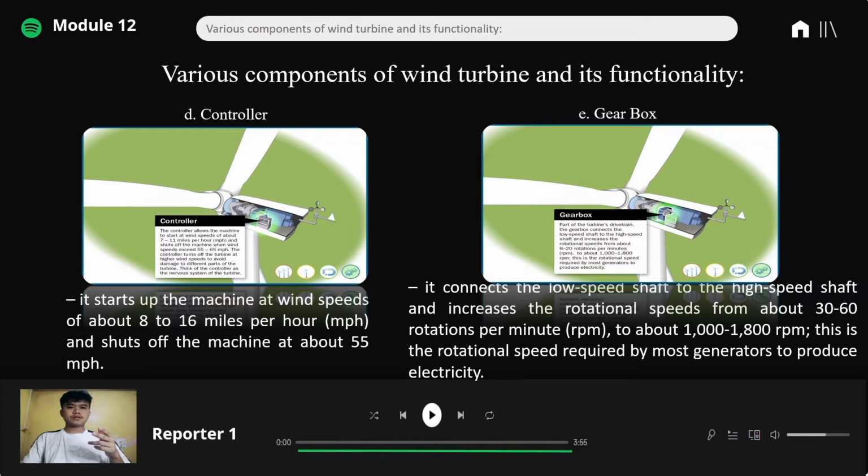It is a part of the wind turbine, and engineers are exploring direct drive generators that operate at lower rotational speeds and don't need gearboxes. So for lower rotational speeds, gearboxes are sometimes no longer necessary, but the most common windmills in the Philippines use a gearbox. A gearbox is often used in a wind turbine to increase the rotational speed from a low-speed main shaft to a high-speed shaft connecting with an electrical generator. The gears in a wind turbine gearbox are subjected to severe cyclic loading due to variable wind loads that are stochastic in nature.